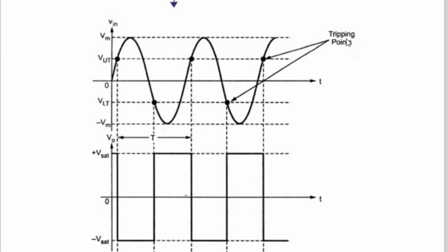Triggering means changing in the voltage level of the op amp from HVL to LVL or vice versa, LVL to HVL. So this graph is also very simple, but this graph is a condensed or compressed graph. So here is the change in the voltage level from HVL to LVL in the beginning. In the beginning, the output of the inverting Schmitt trigger is in HVL. So here for a small time HVL is there.